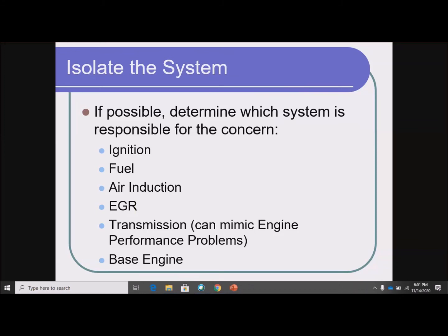Fuel problem, what's your concern? If you have a lack of power, maybe your fuel pressure is low. If you have a misfire, maybe you've got a bad injector. Air induction, we could have vacuum leaks. We could have leaks in the air inlet tube between the mass airflow sensor and the throttle body. These are all the different systems, the different sorts of things that they can cause. EGR can cause stalling, things like that.